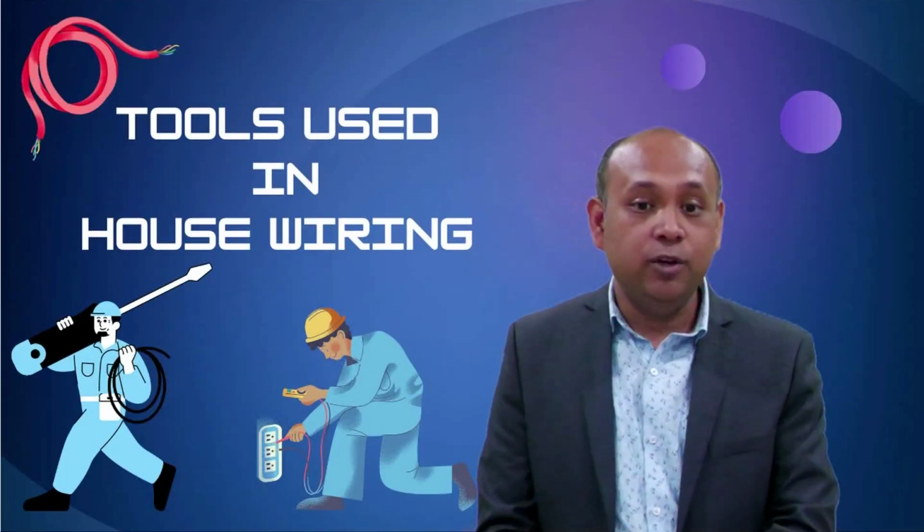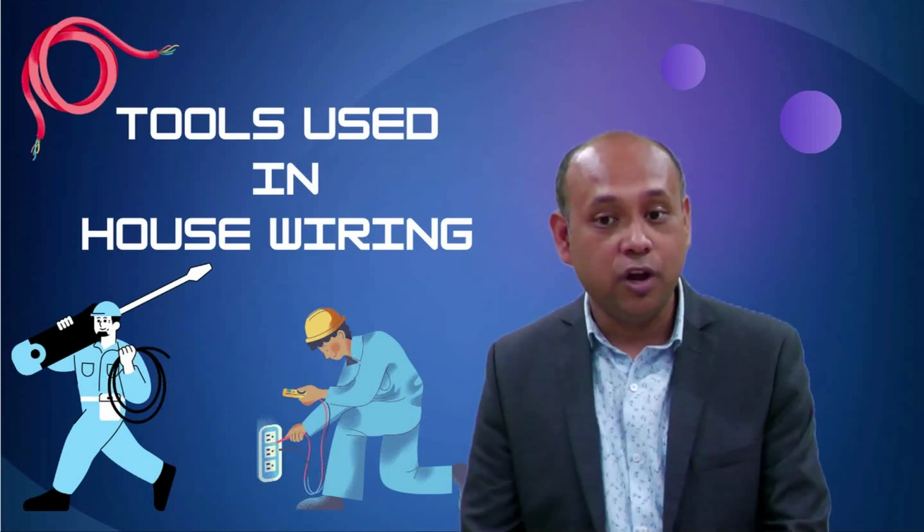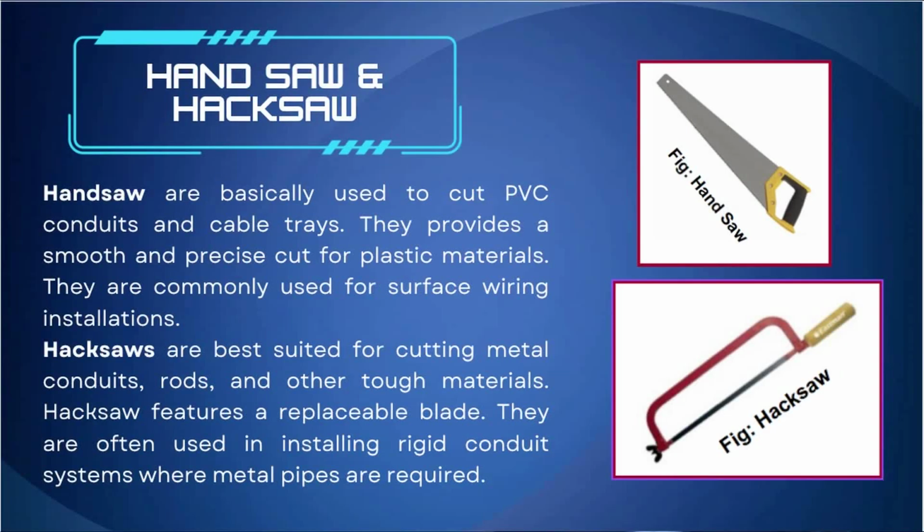Other tools used for cutting purposes are the handsaw and the hacksaw. Handsaws are basically used to cut PVC conduits and cable trays. They provide a smooth and precise cut for plastic materials. They are commonly used for surface wiring installations. Hacksaws are best suited for cutting metal conduits, rods, and other tough materials. Hacksaw features a replaceable blade. They are often used in installing rigid conduit systems where metal pipes are required.